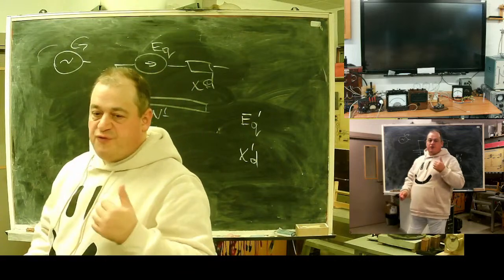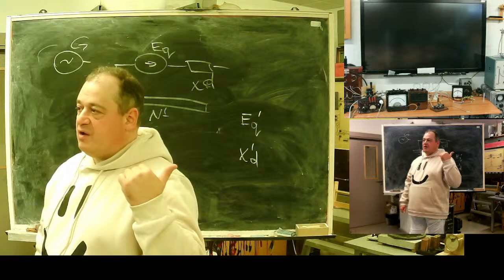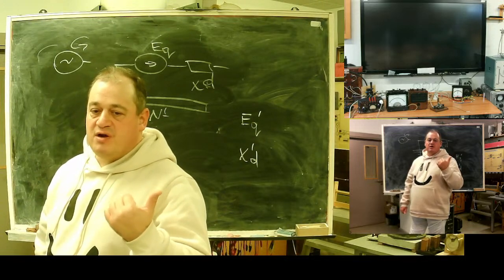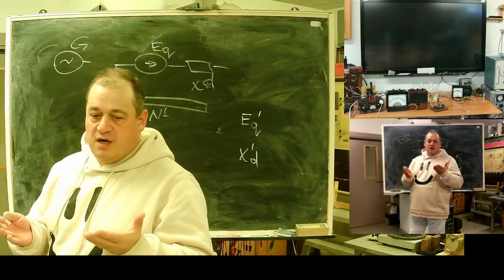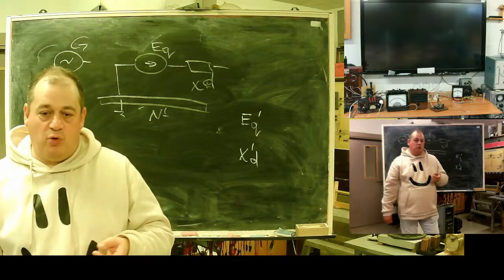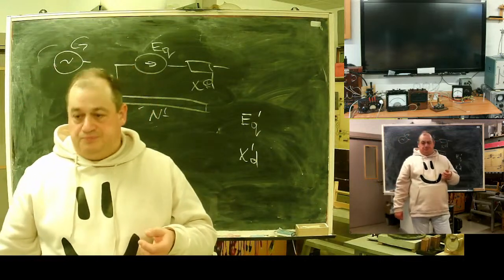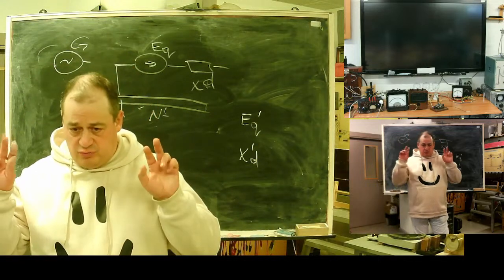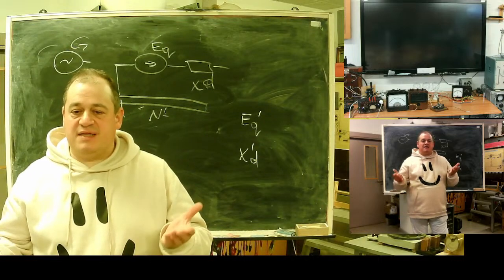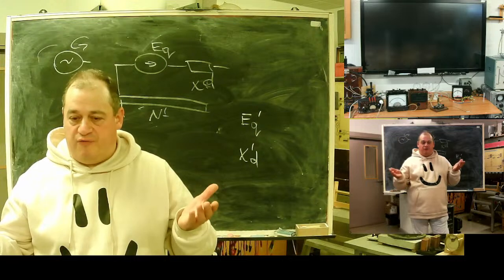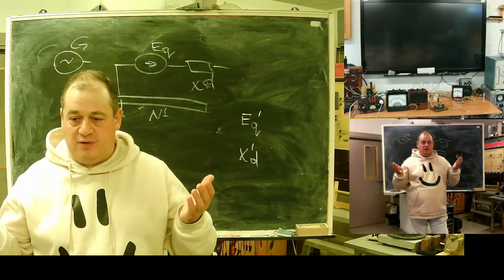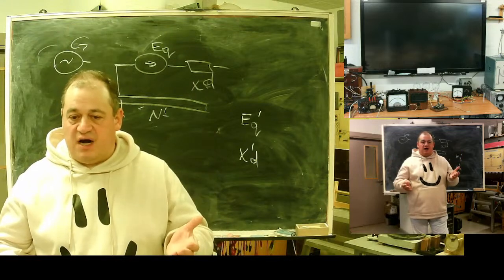This can cause very fast degradation of the machine bearing. The lower bearing on a modern machine is rubber or some composite, lubricated with water. It's a water-immersed bearing. This bearing takes all the weight of the rotor with its turbine wheel, 500, 700 tons.